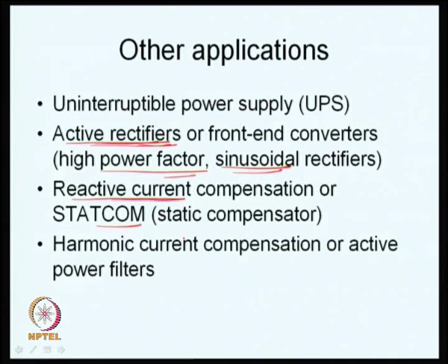And once again, if you have non-linear loads which may be drawing harmonic currents, it is possible for you to supply these harmonic currents using a voltage source converter. That is called harmonic current compensation or active power filtering. So, these are some applications, namely active rectifiers, reactive current compensation and harmonic current compensation. These are some issues and applications of voltage source converters which we will discuss in our next lecture.